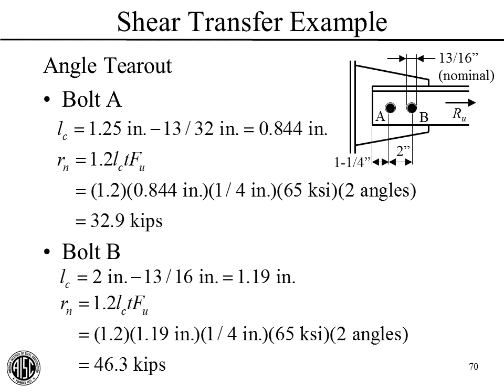Okay, well, it comes from this. Take a look at the L sub C, the distance or the length parallel to the load of the shear plane of the shear failure. Now that's going to be measured from the end of this angle parallel to the load over to the edge of the hole.